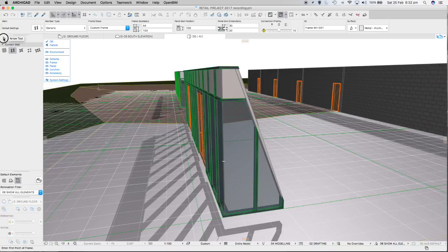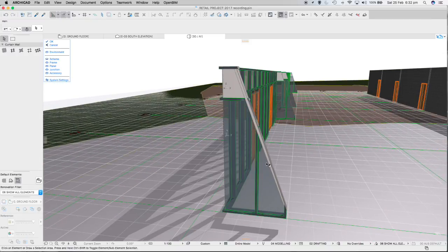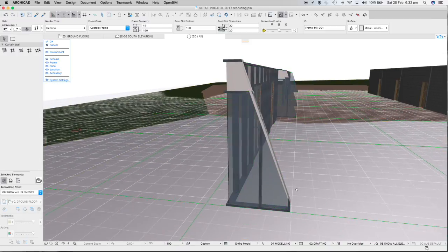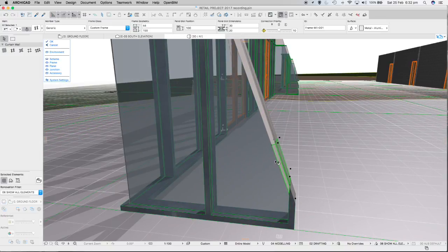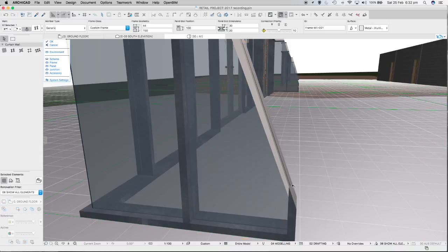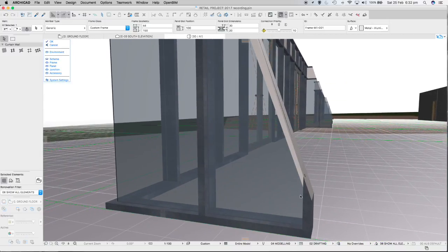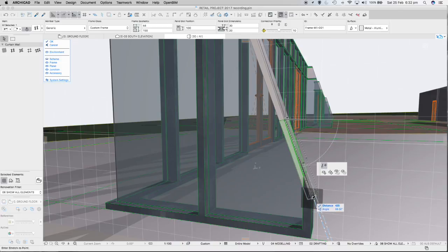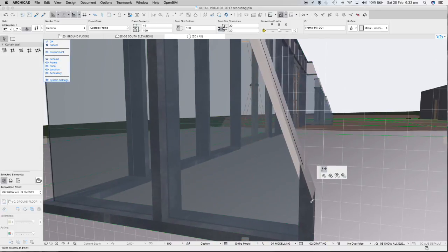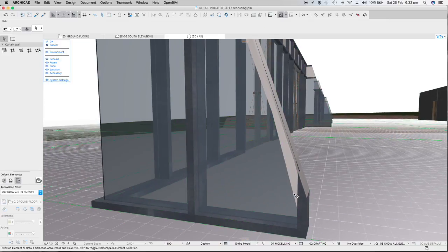So you can see I have placed a frame tool that's going to now have to be readjusted. So you can click on it, it puts it into different segments though, however, and it's just a matter then, I suppose, if you really want to, of readjusting the ends of these segments. Like I suppose that end point there, we want to come down to this end here. But you've got to get it to snap to the end, and it doesn't seem to really want to do that.